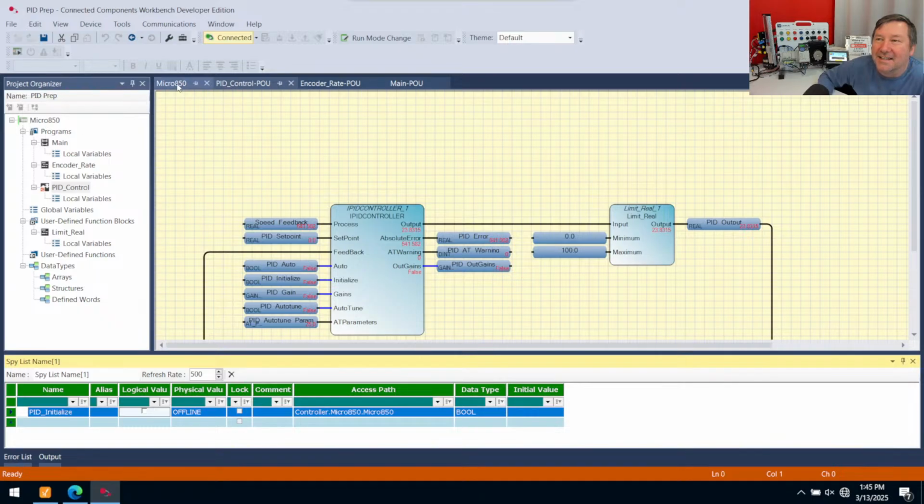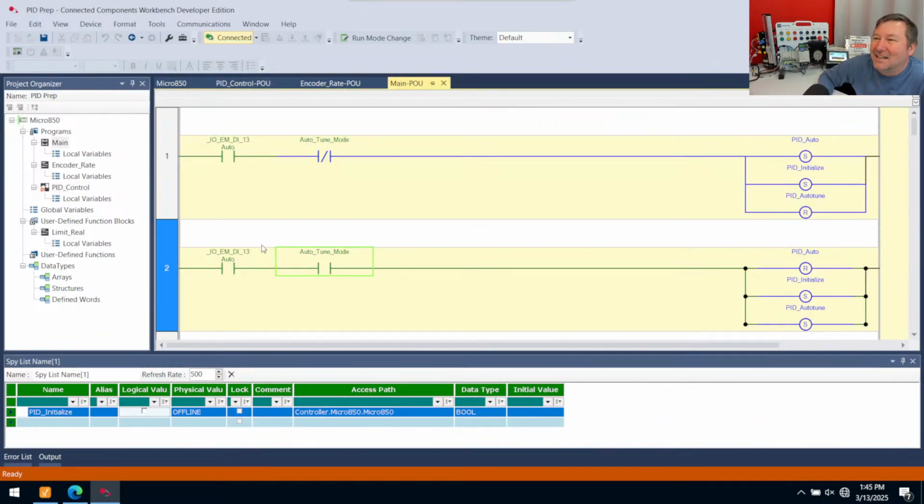The whole point of the set and unset from earlier was I only wanted these to write one time. I'm going to look for a 1 here. There should be a pulse, or in Studio 5000, we would call it a one-shot. So a couple things. This is a good learning opportunity. You want to get everything out of it. So hold on. Don't go offline yet.